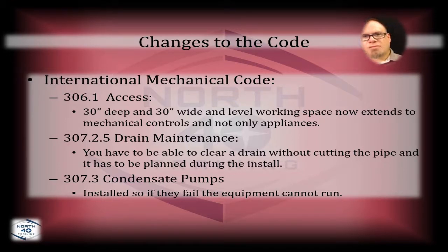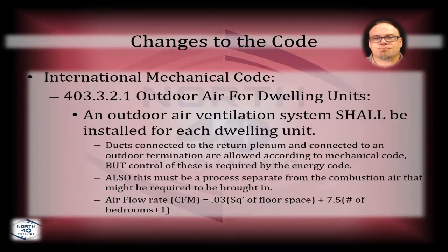So if a condensate pump is your primary source of condensate, taking that water over to a drain someplace, then you have to have the overflow hooked up, right? And that basically ties everything back into the equipment. So if it starts to overflow, the float switch comes up, it'll cut off the appliance from running. And that's the main thing. You've got to have that hooked into the low voltage so that before it overflows, it shuts everything down.